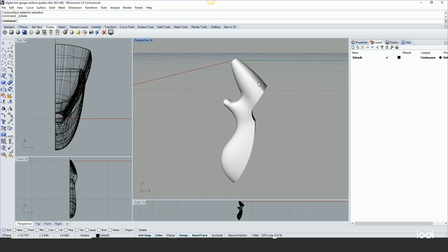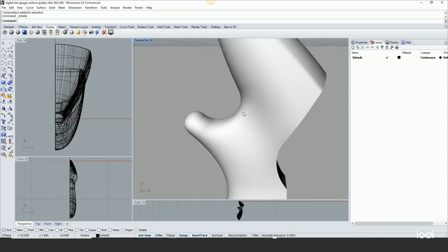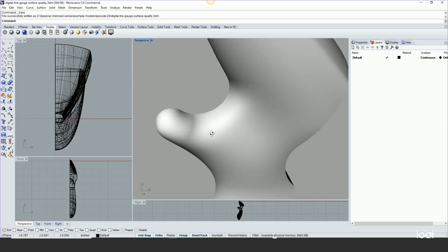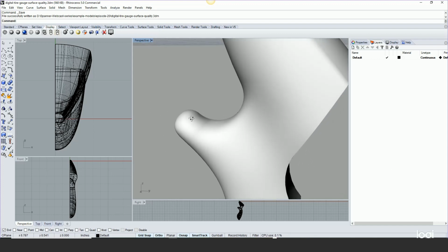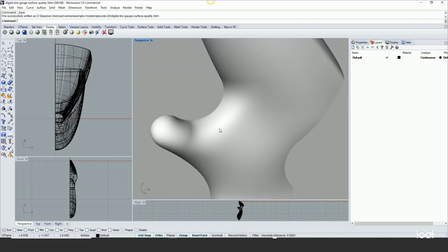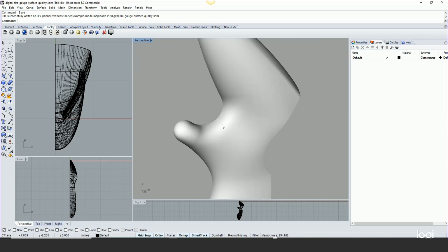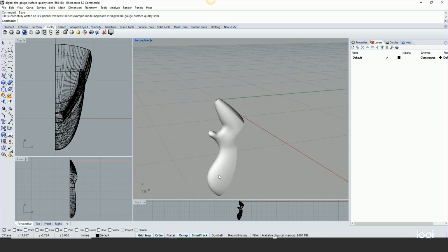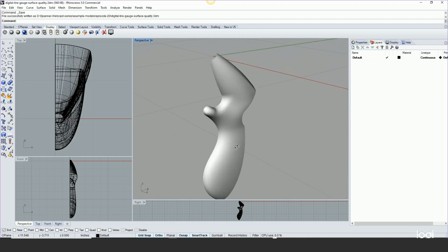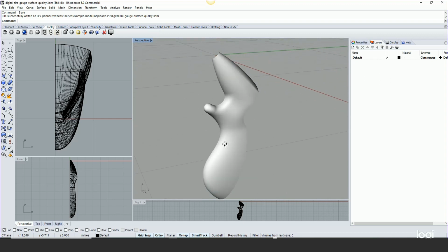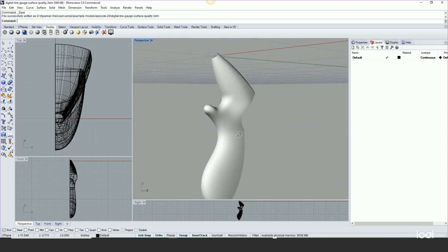And immediately you'll notice, and what the industrial designer would notice, that there's a bit of discontinuity going on right here near the end of this trigger. You can't see this in SolidWorks. It's the way that Rhino shades their models. One of the factors there that I think is pretty interesting in Rhino, unlike SolidWorks, is that when you rotate your model, your lights are stationary, but your model space is rotating. So this kind of acts as an analysis tool. As you rotate things around, the lights move smoothly over the surface.